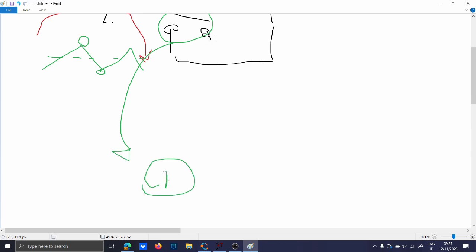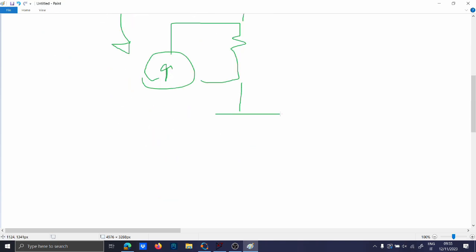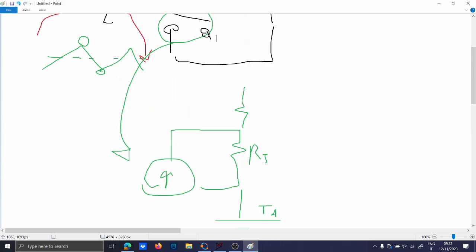into a thermal model, which is made more or less like this. This is the ambient temperature, and these are the junction resistors: junction case, junction ambient, and there is also junction heatsink. You will have the maximum temperature reached here.